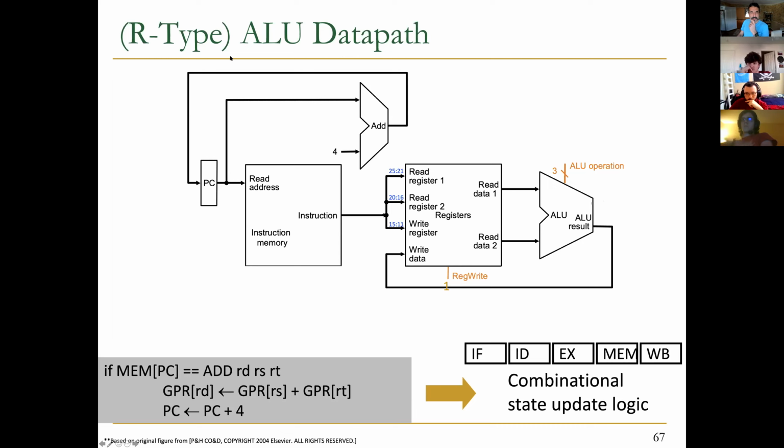So let's focus on this part. You definitely need an adder. An adder is again logic gates that you give 2 numbers, and it adds them up together. In this case, you need one number coming out of the PC, and the other one is a static 4. You always need to add 4 to it most of the time, but you should guess that sometimes you may need to add different numbers. We will get there when we discuss jump. But for now, by default, we add 4 to PC, and the result will be written back to PC. Hopefully this part is clear.